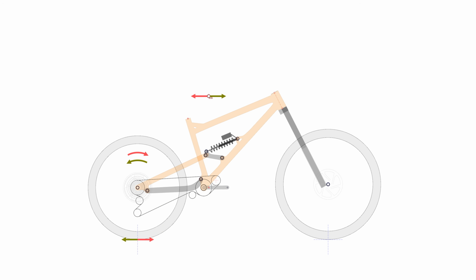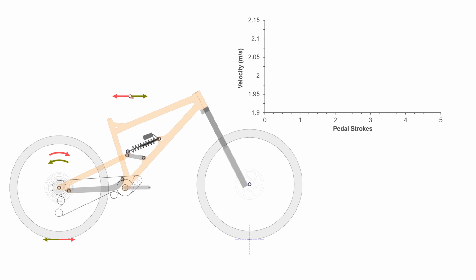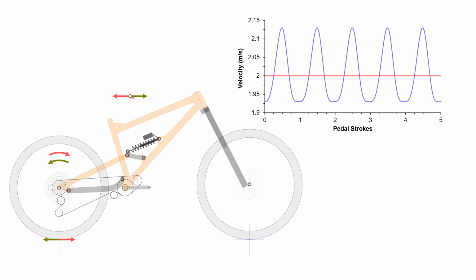Both cause a reaction force at the ground contact patch, and both make the suspension respond to a change in weight distribution. So every time the bike feels any kind of acceleration, the suspension will want to react in some way. This is especially noticeable during pedaling. Even if a rider tries to pedal smoothly at a constant cadence, in reality, each pedal stroke contains small accelerations and decelerations. That movement creates a rocking effect, which constantly wastes energy that could otherwise drive the bike forward.